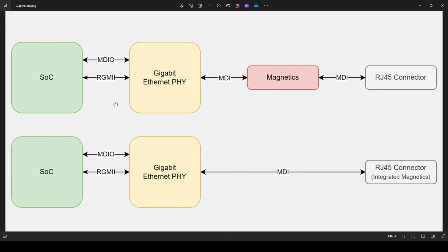This is our high-speed data transfer, but to actually configure the Ethernet physical layer, for example, to set auto negotiation, to set maybe what the LEDs do, we will need another configuration interface, and this is MDIO, the management data interface. You can think of that very similarly to I2C or SMBus, with a unidirectional clock line where the MAC drives the PHY, and a bidirectional data line for transfer of control data between our MAC and our physical layer.